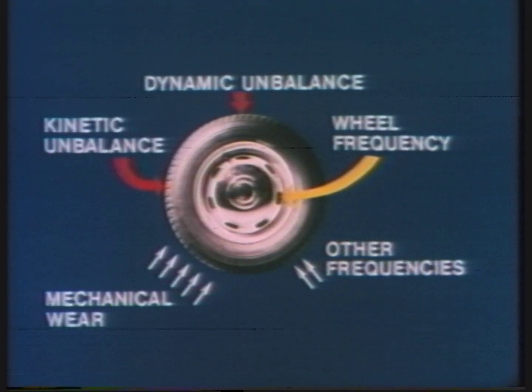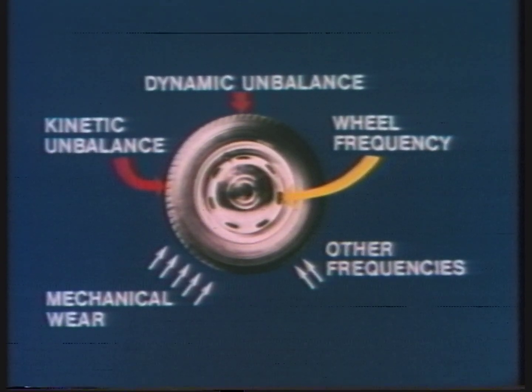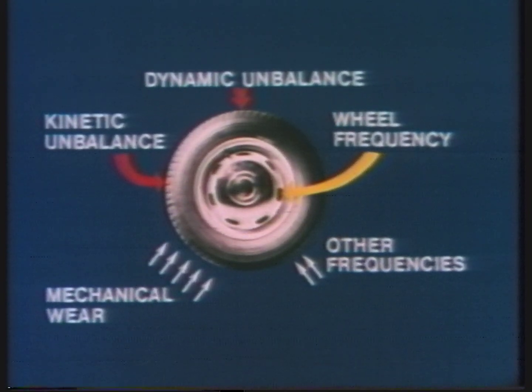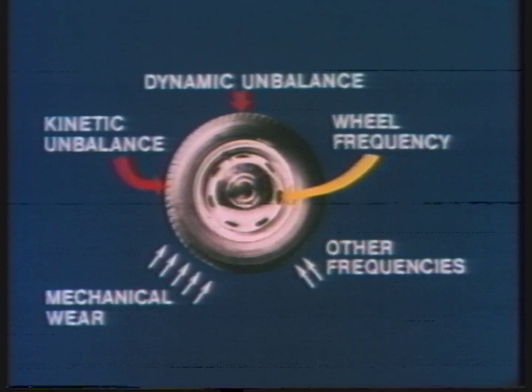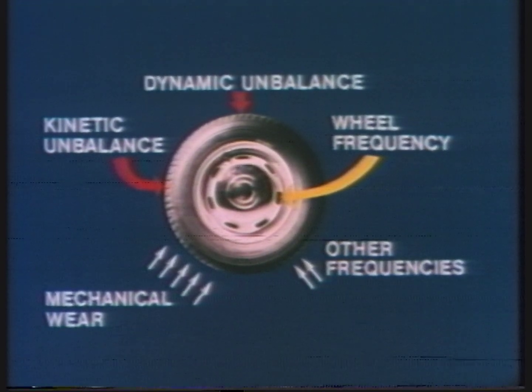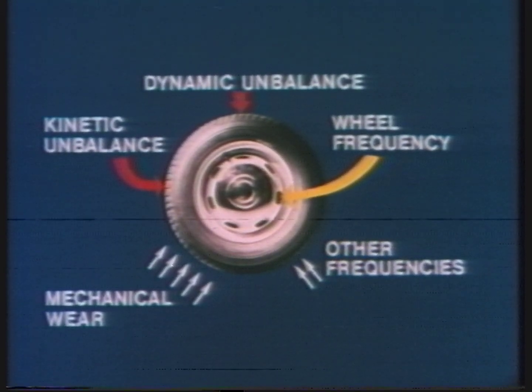But you may have kinetic and dynamic unbalance, together with wheel and other frequencies, all magnified by one or more mechanical conditions as components begin to wear. Nevertheless, correct lead-up to routine wheel balance and careful attention to kinetic balancing will in most cases take care of all problems. Although detailed wheel balancing procedure is not within the scope of this program, there are one or two points which seem to get overlooked in the preparation work. These in themselves can waste time and cause endless trouble.